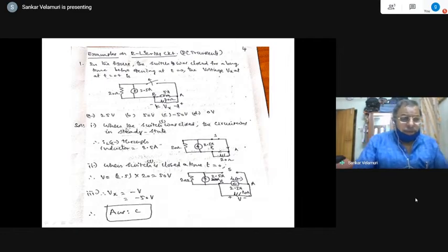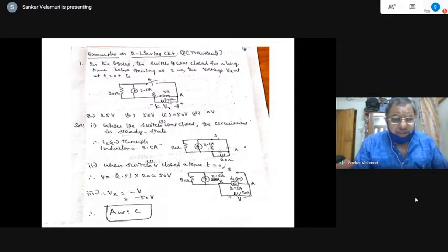So anyway, now let me come to the actual solution to this. So when the switch was closed, the circuit was in steady state. Okay. So this is the equivalent circuit when the switch is closed, before it is opened. That is called steady state condition. This steady state current will become the initial current at the time of the opening of the switch, where you have to find the corresponding current at time t equal to 0 plus, just immediately after that. That is the meaning of this, right? So that is how these particular things are being considered, right? So that is the meaning of the switch was closed for a long time. That is, steady state current would have been raised in the circuit element.